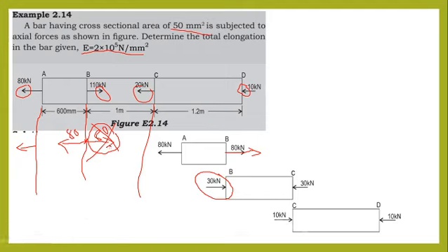So we cannot simply add force to a system that is already in equilibrium. We cannot simply add a force to an equilibrium system. So I will be cancelling the force added to the system. The 80 kilonewton force is taken from here and it is displayed here. Now the system has 80 kilonewton towards left. So when I am analyzing this section B, it has 80 kilonewton towards left and 110 kilonewton towards right. In net effect, it has a 30 kilonewton force towards right.